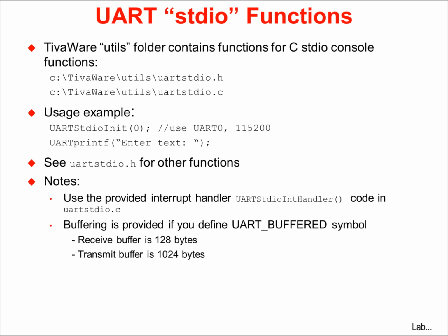TivaWare's UART library includes standard I/O console functions for initialization, printf, get, flushing the FIFOs, and others. To use the functions, you should use the interrupt handler provided in UARTstdio.c.